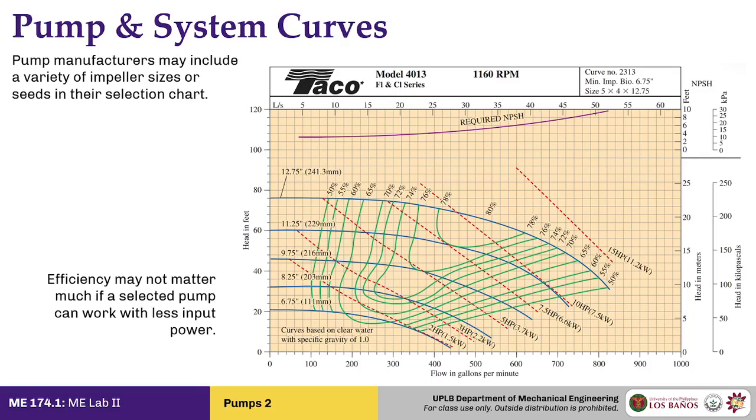I'm not sure if this is reflected in your ME thermodynamics, but normally when you are given a Rankine system problem, the efficiency of the turbine is around 80% and above. But when you are given a particular efficiency of the pump, it's usually 80% and below. It never breaches 90 or 85 ever.